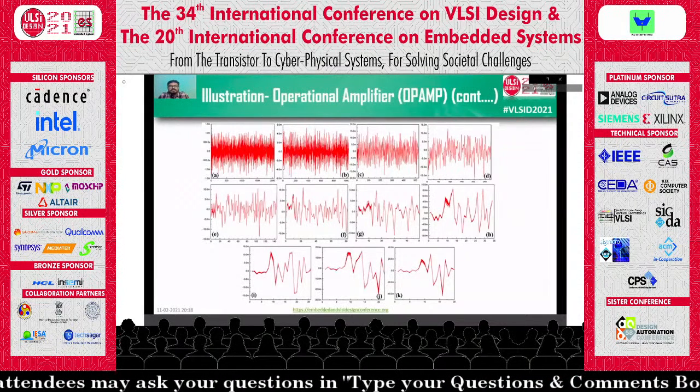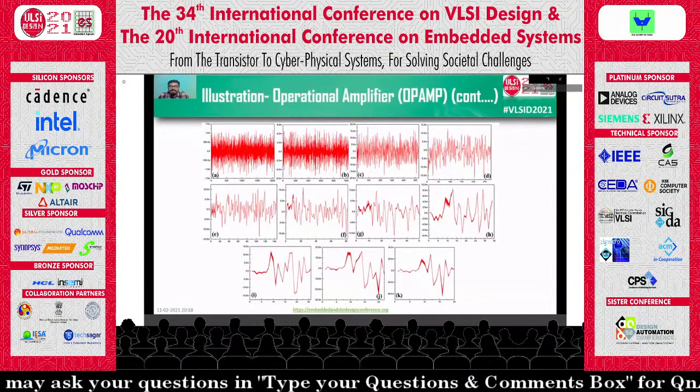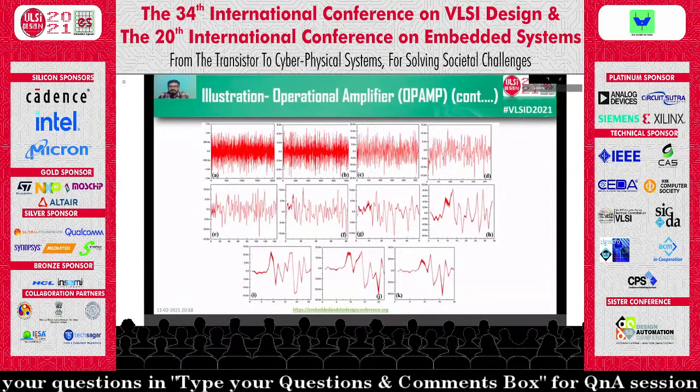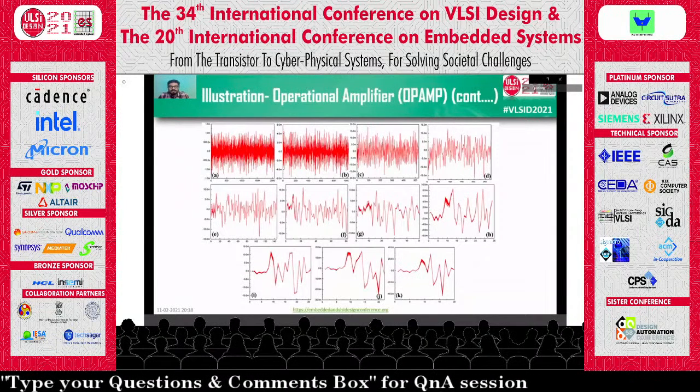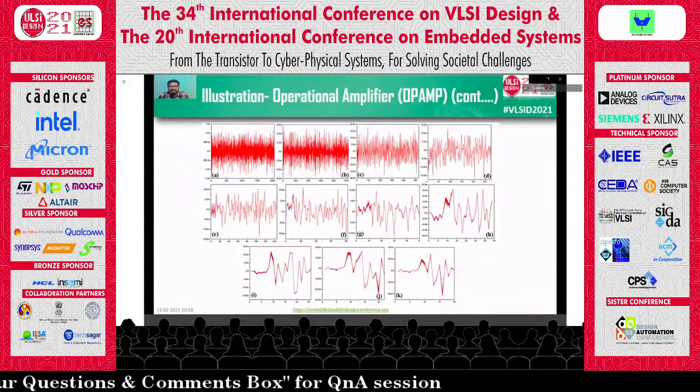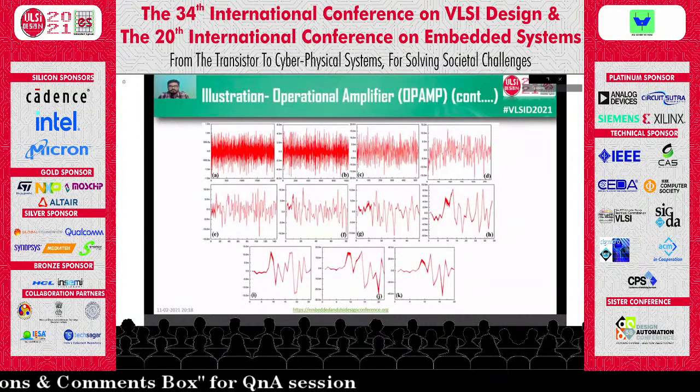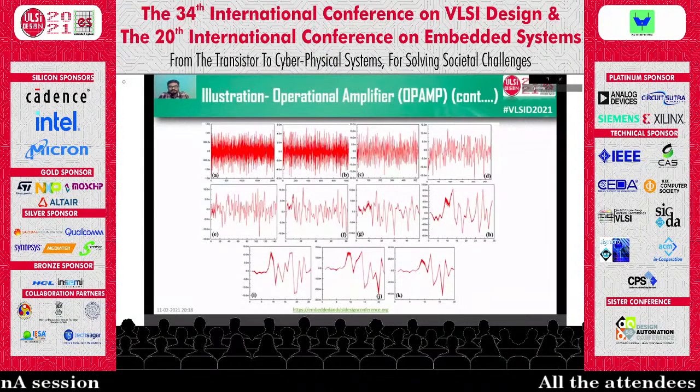The low pass filter output, which also consists of 2048 samples but spread within the 0 to 125 MHz frequency band, is further decomposed by passing it into a low pass and high pass filter, generating subsampled signals with 1024 samples. This procedure can be continued till 1 DWT coefficient can be calculated.